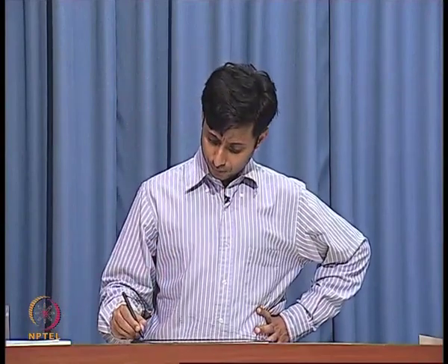Okay. So, we are going to summarize the entire module with this. In this module, we first started with resistors, then we worked on capacitors, and then we worked on inductors, and after that we worked on transmission lines or wires rather. So, under resistors we just discussed the units. Ohms per square was the unit, and if a surface resistivity is given to you, you can figure out by counting the number of squares in the track what is the resistance of the track. That is, as far as resistance goes, it is easy.